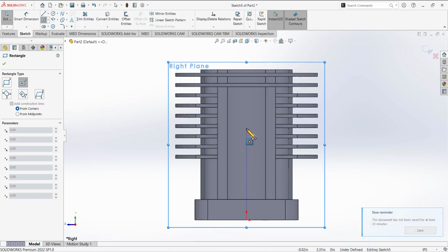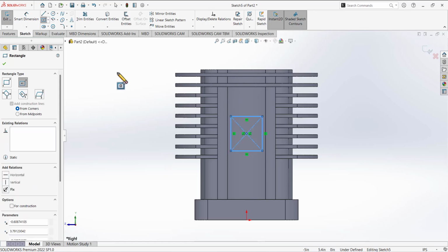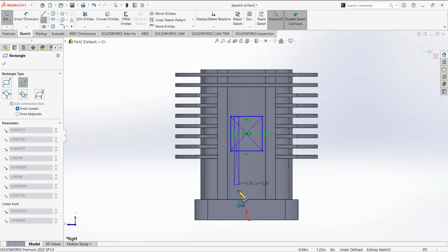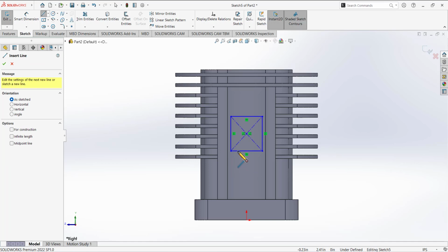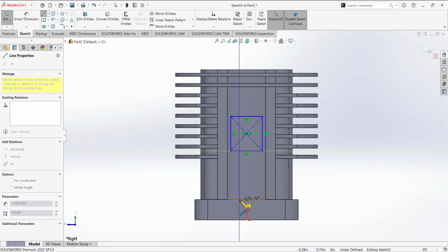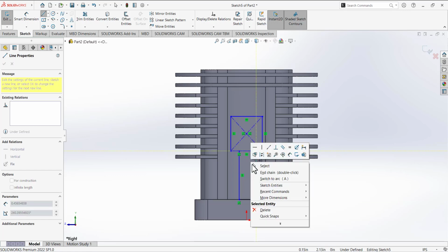For this sketch, we are going to use a corner rectangle first, and make sure it auto-tracks, so the corner is the center of this corner rectangle, on this region like that. Then use the line tool, not the rectangle, and draw a line starting from this point and ending on this edge, moving horizontal and then above, and the second point is coincident on this edge.